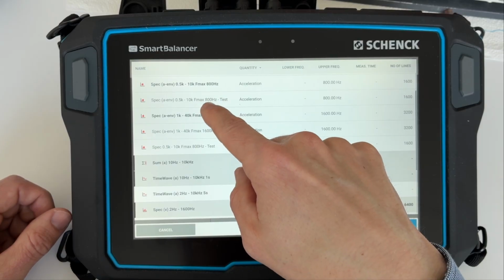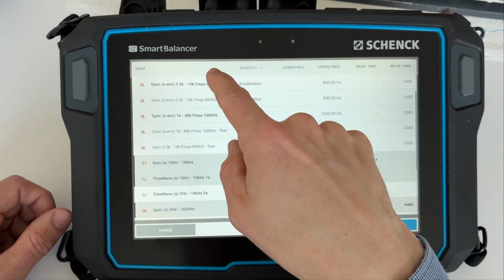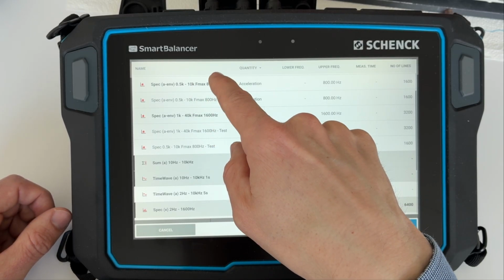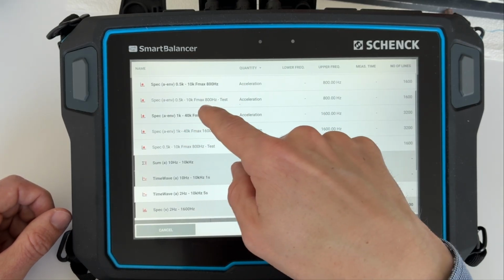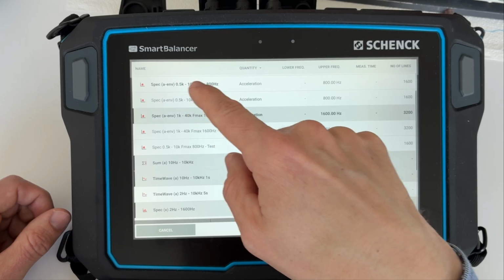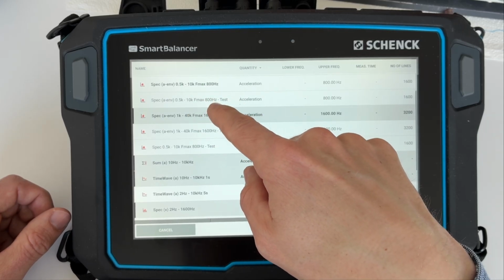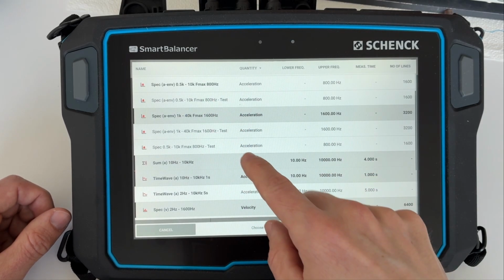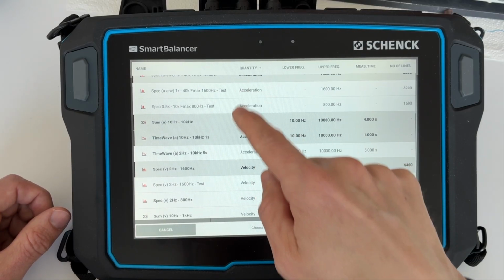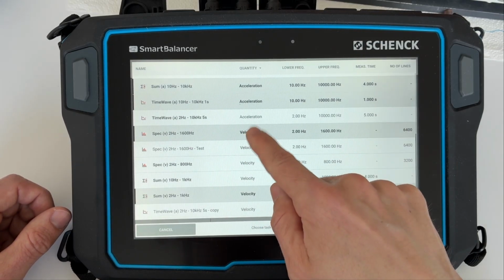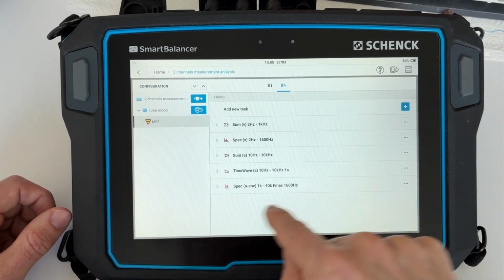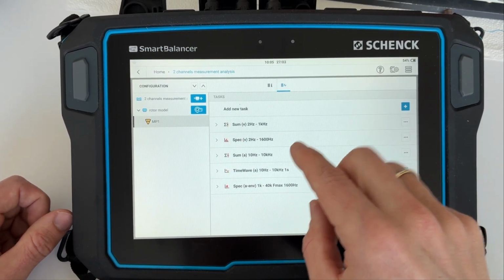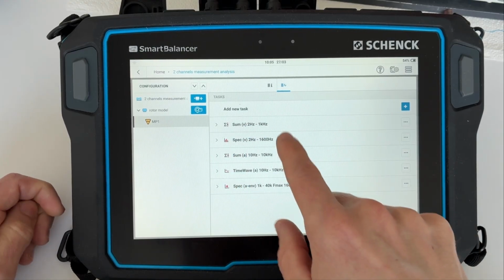We take also envelope signal, envelope spectrum. We take here, for example, 1 kilohertz to 40 kilohertz. And this we add to our measuring point. So this one is complete.